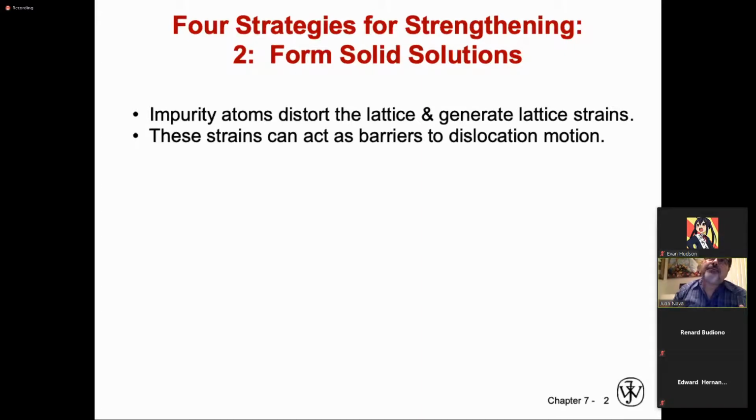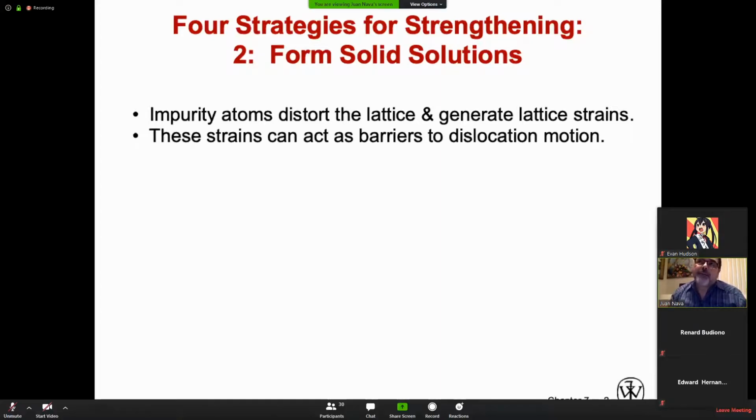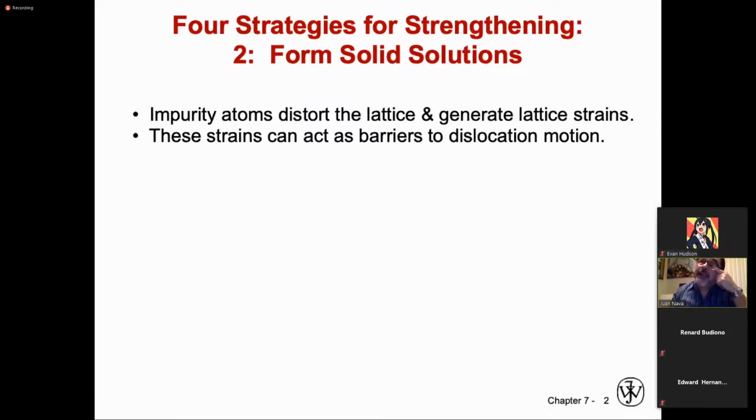But then you have these other phase diagrams that show limited solubility, meaning in the solid state, you have different phases that can be formed as a function of composition. At that moment, I ask you, which type of alloy, the isomorphous or the limited solubility, has the largest strength? The limited solubility. Why is that? Because the limited solubility has violated any of the 4 rules, and the most likely rule violated, because it's the most important, is the atomic radii difference.